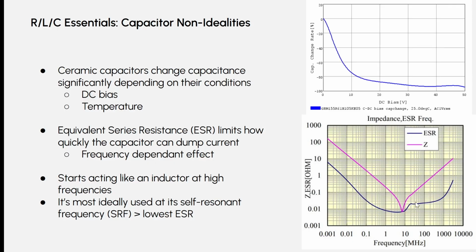So anyways, what you'll notice is that funny stuff starts happening again around 1 to 10 megahertz. This is relatively high, but just keep that in mind when you're working with higher frequency stuff. But for power decoupling on a microcontroller, you don't have to worry about this. But power electronics design, like actually converting tens of watts between different voltages, you do really need to consider this.